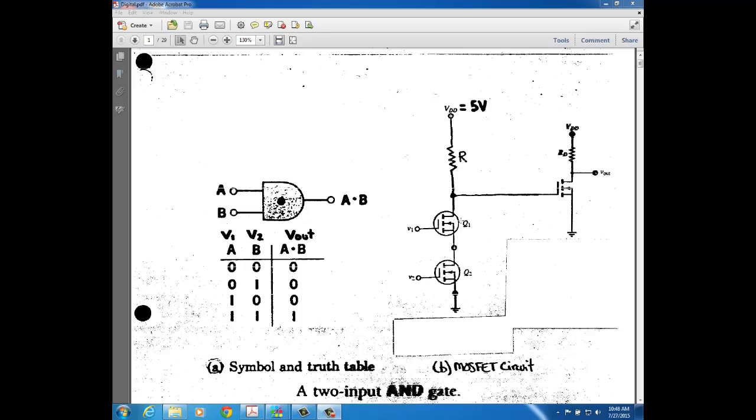And then from drain to source you have your channel, and when that voltage is one value, the channel acts as an open, and when it's the other value, it acts as a short. So we're just doing the ideal analysis here. Where we have zeros and ones, a 0 is 0 volts, a 1 is plus voltage, which is enough voltage to make this channel ideally a short.